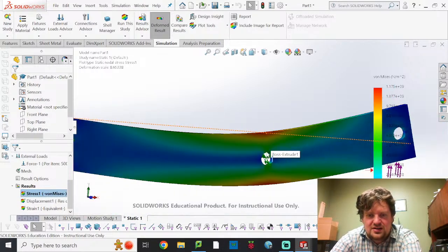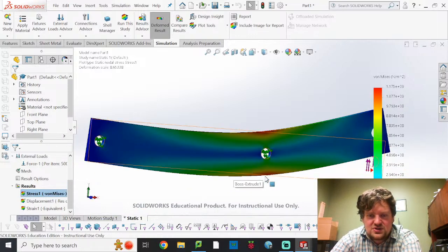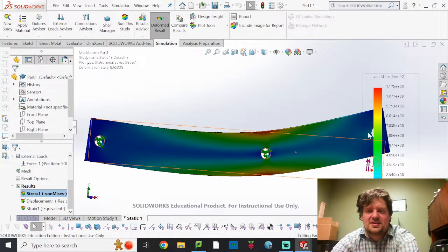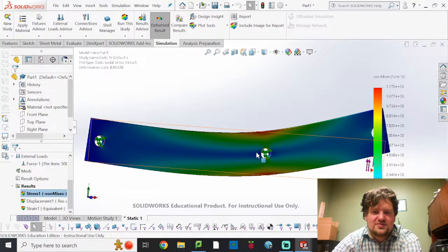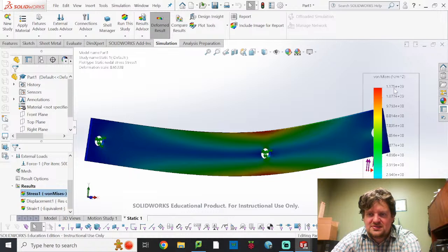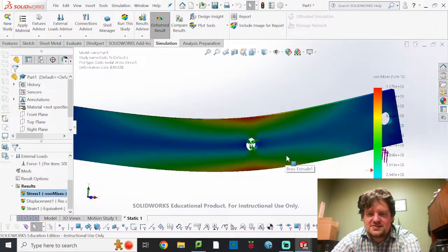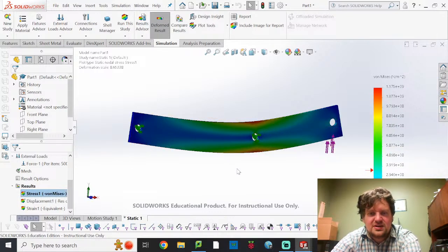Now, in our understanding, this is going to be your highest bending moment. It's about right here. So I'm not shocked by that. About 5,000 pounds times whatever this distance is. Yeah, that's going to be where our maximum bending moment is. So, yep. Then what we would say is our max von Mises value is going to be this stress right here occurring at that location. Take a screenshot of this, and this would show up in your paper for your analysis of this part.